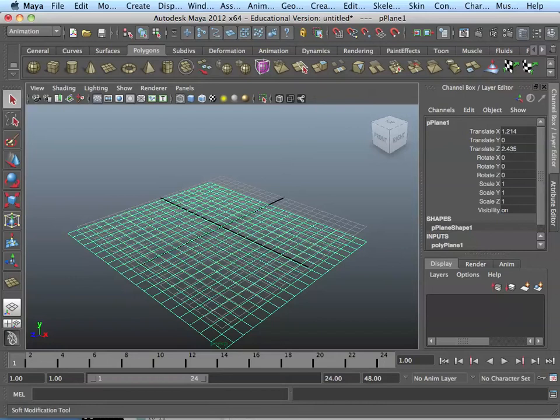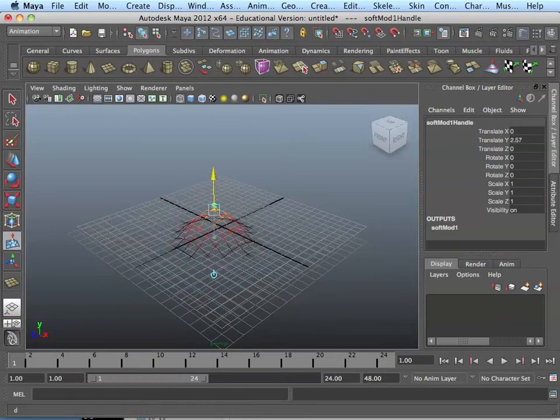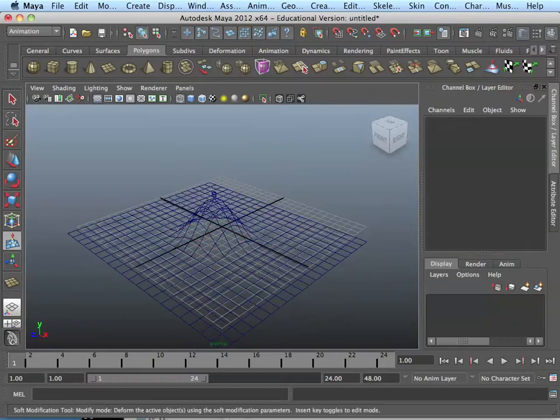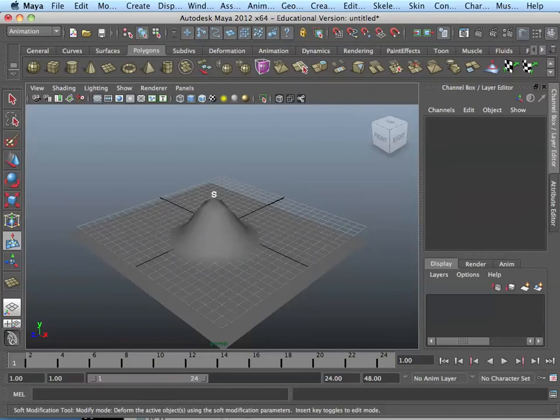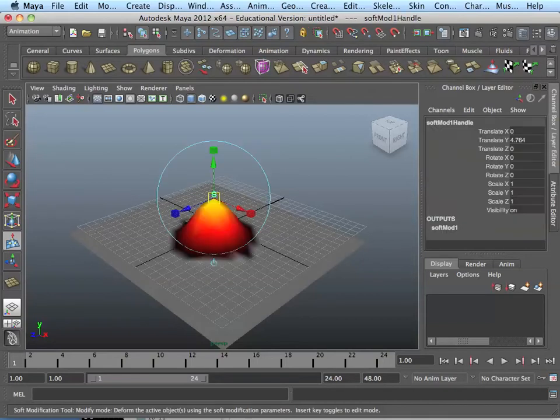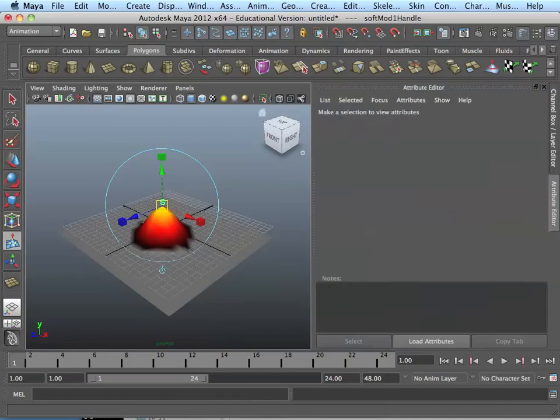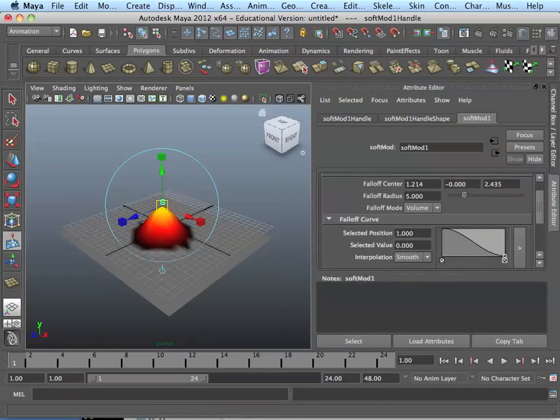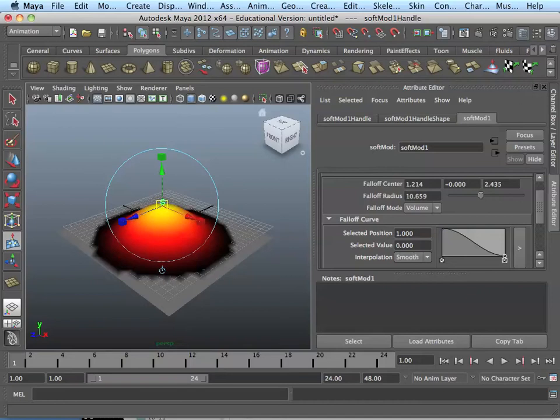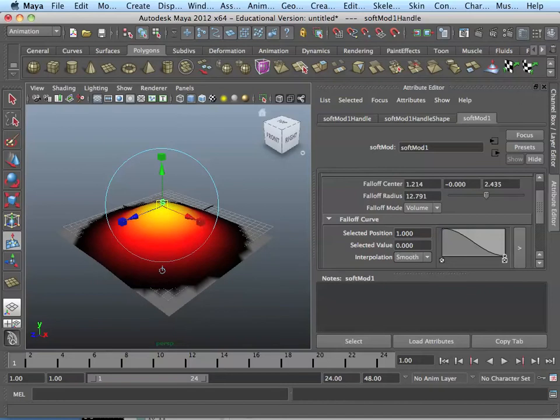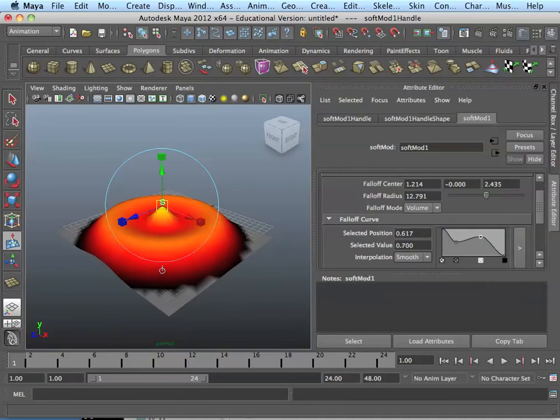And the question came last time, what is the soft selection? Right, so I have a polysurface, and normally I could either just pull a vertex or pull the surface. Soft selection lets you start from a point and then create a falloff. So if I pick it and then go to the attribute editor, it has the radius, even the curve on how it falls off. It's a sweet little tool. It's very simple, but it's a very nice little tool.